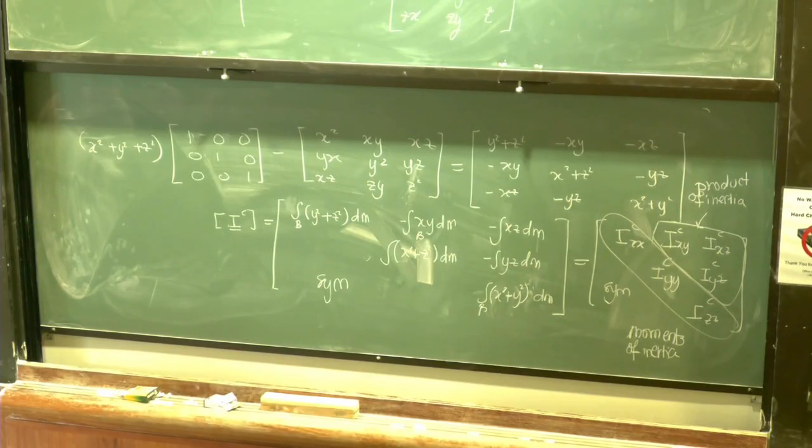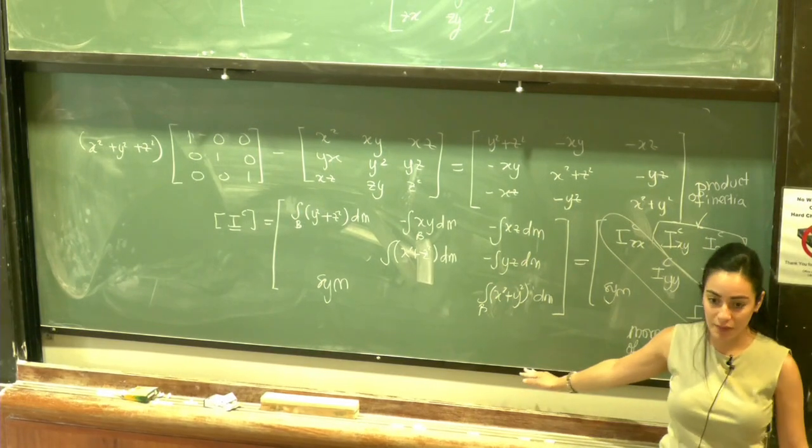Okay, so again, question. If I have a person standing like this versus a person standing with their arms open, and I'll take the axis to be like this, is the moment of inertia I_C zz greater for this person or for that person? Person A or person B? B. B has greater I_C zz, right? Because the mass distribution about this axis is greater. And we can see that this term is measuring the mass distribution about that axis.